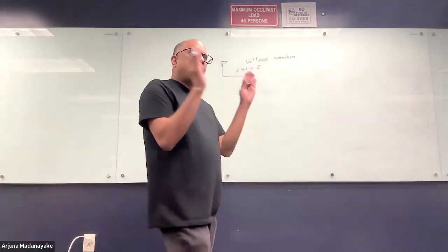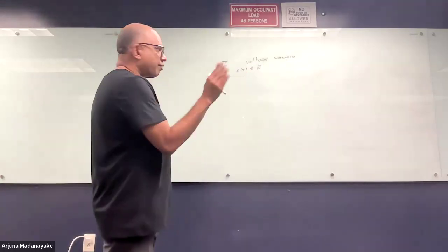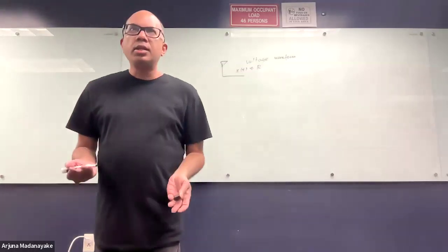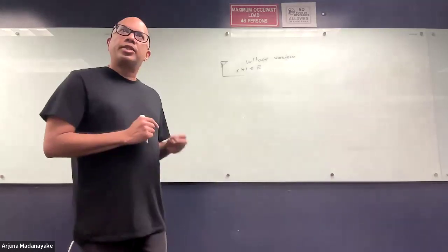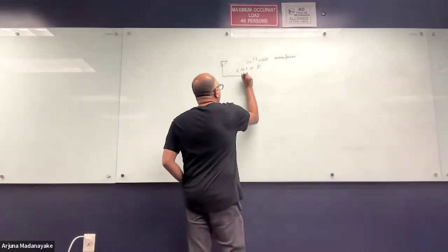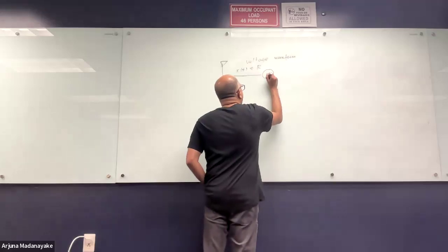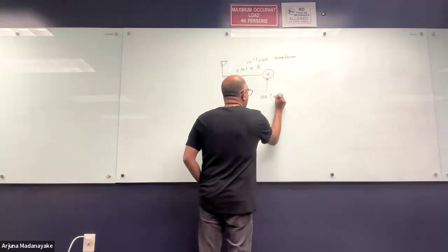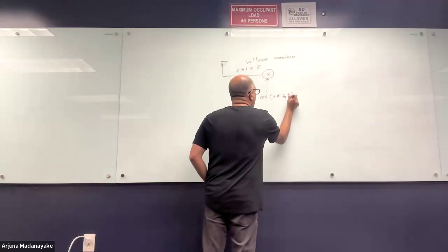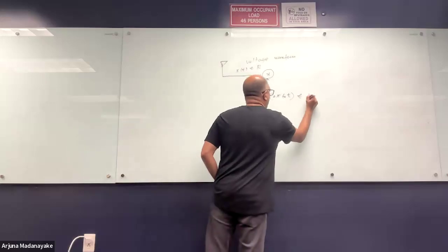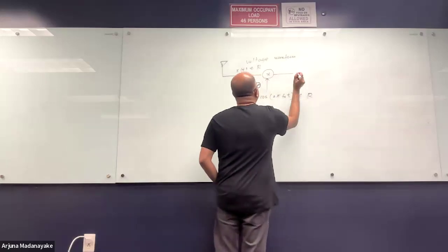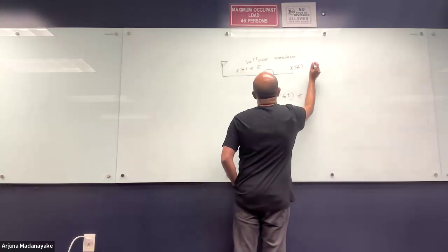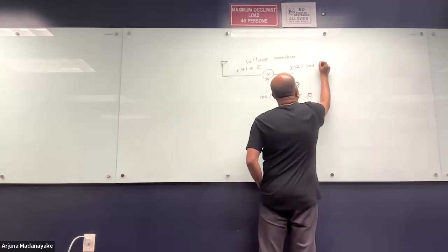So you want to change the frequency variable f by f0 by changing the frequency domain, but we don't have access to imaginary signals. We only have real valued signals. So the closest real valued signal that we have would be a cos wave. Let's say I'm going to multiply it by cos 2 pi f0, which is real value. Produce the modulated output or frequency translated output x of t cos 2 pi f0 t.